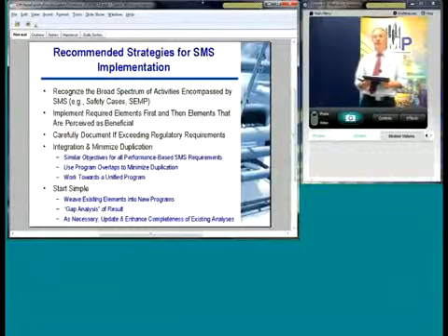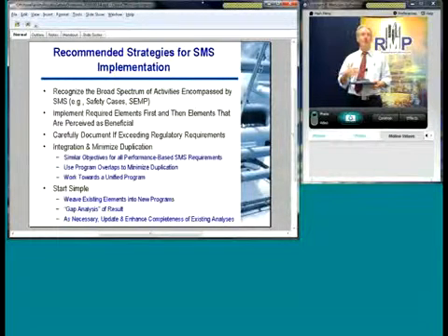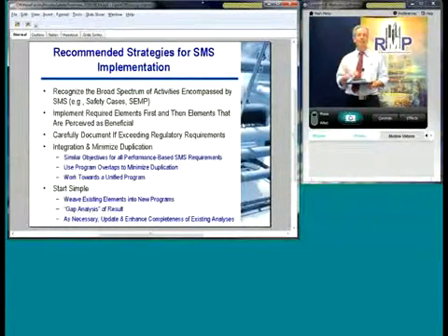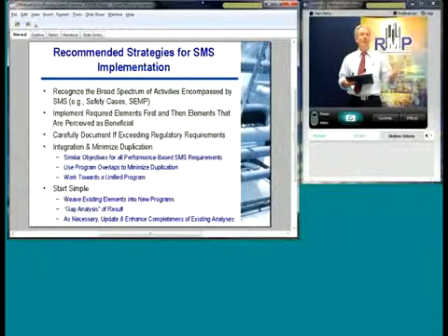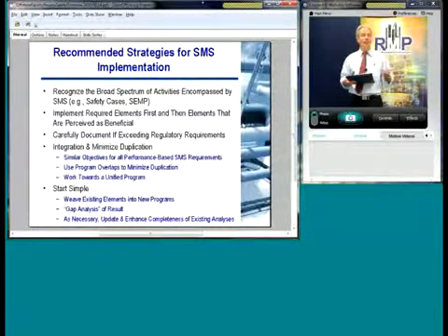We go to so many facilities and see different documents for process safety management, risk management programs, for offshore facilities that have onshore counterparts in the same business units. Sometimes you'll see a SEMP document and a PSM document. That's really unnecessary. A lot of the elements, the techniques you use are common, so why not have a unified program so that it's more robust and easier to manage.